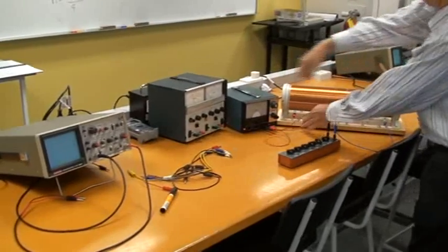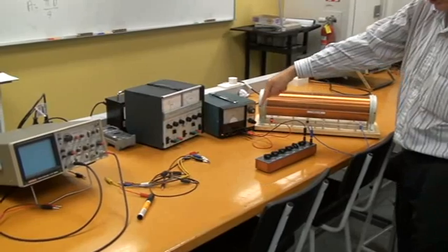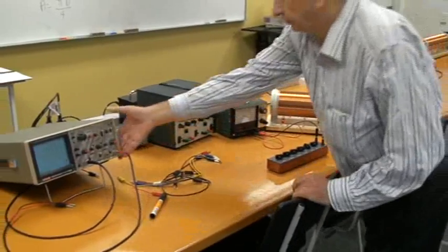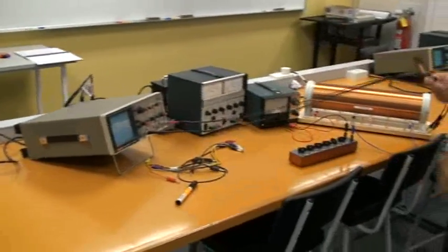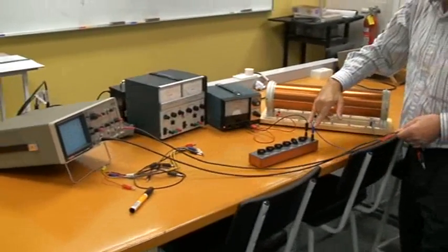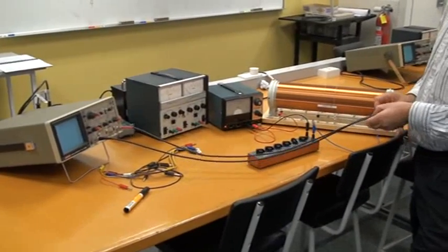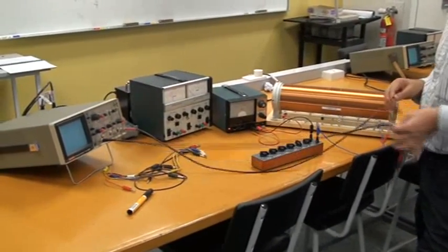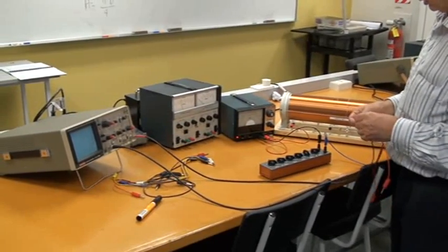It's going to be current flowing around this circuit from the supply, through the coil, through the resistance, back to ground. Now, what happens next is we're going to use the oscilloscope to measure the voltage across the resistance and also the voltage across the coil. In this way we can figure out what L is. So remember, we always must be careful with an oscilloscope to put the earth in the right place.